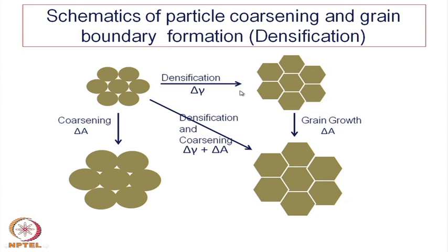The other alternative is what we call the densification. That means this kind of a loose powder changes its configuration and makes a strongly bonded powder. So, they are now strongly bonded, the size and shape have changed, and there are greater particle to particle contact or solid to solid contacts. So, these white lines are actually called the grain boundaries, and the larger pores have gone out.